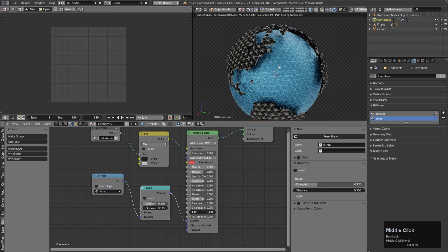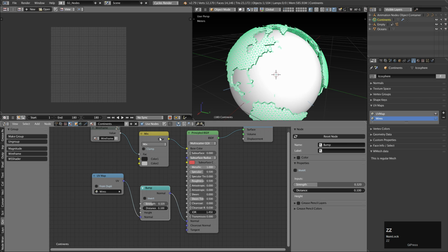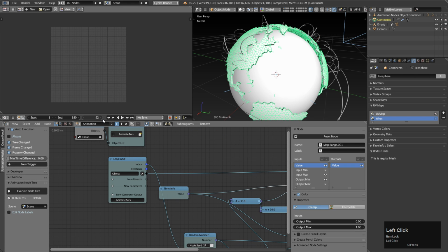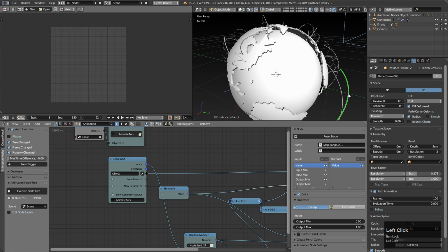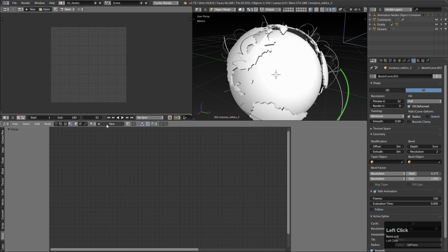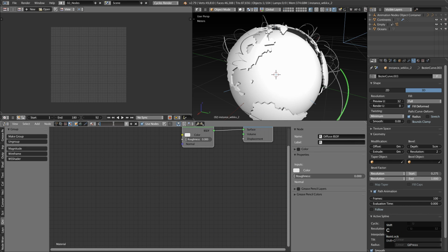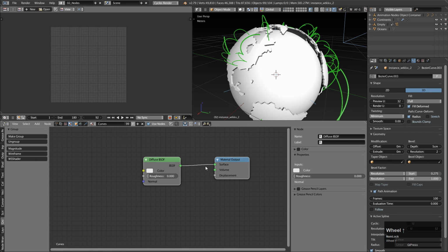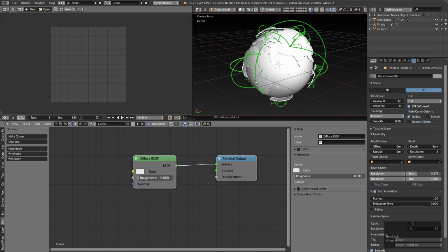After that, we can make shader for the curves. Don't forget to go back to the object mode, of course. Switch to some frame where the curves are visible. If you don't see them, you will need to activate the animation nodes again. Select one of them, create a new material for it, and redistribute the material to all of them. They are in the same group. We can use it for the selection, so hit Shift G, pick group, then hit Ctrl L and pick materials.